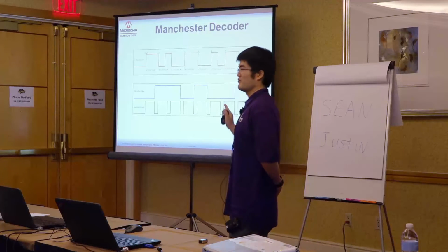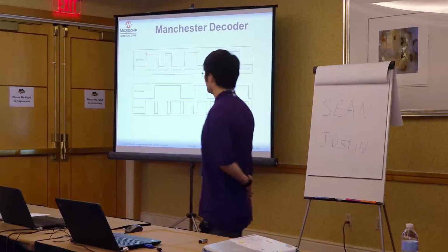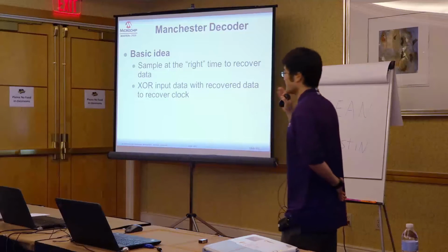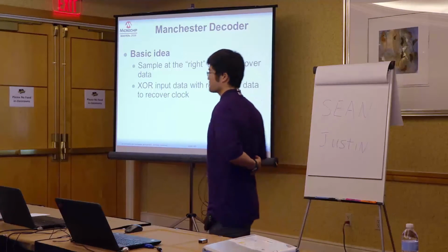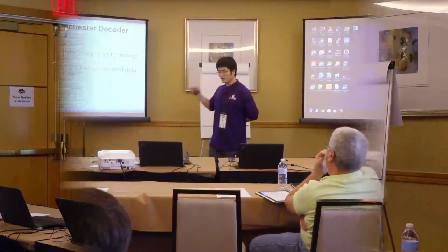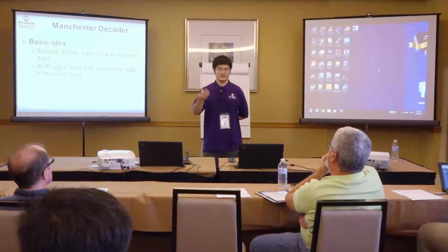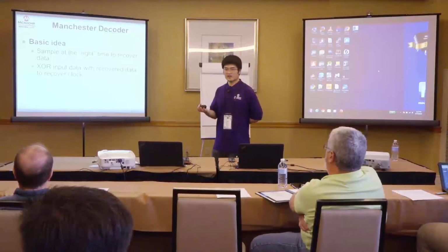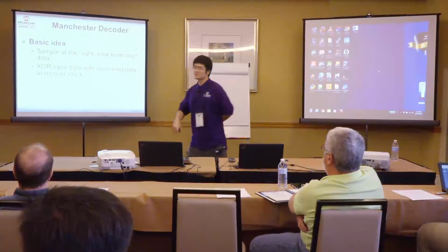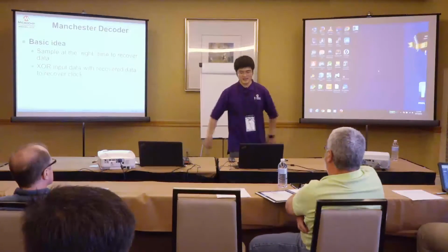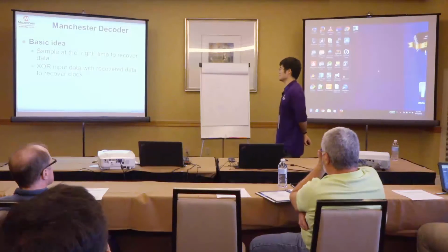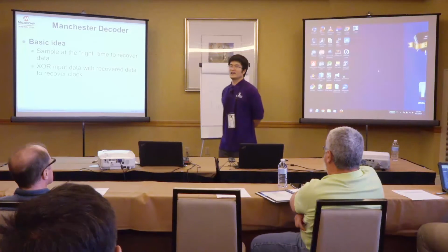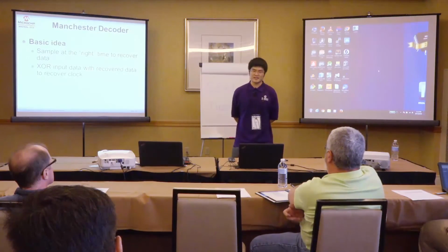Are we good? Everyone good on this side so far? Okay. So that is how you recover the data, right? Now, we've been talking about this based on the assumption that we have the clock, but actually we don't have it yet. Now, how do we recover the clock? Well, if you look into the textbook examples of Manchester code, they say Manchester code is very smart, the clock is in the data, and we can always recover the clock from the data.